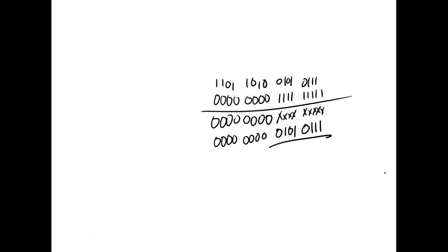So you've got to mask the first bit and work your way back. If I wanted to find out if bit 7 of this input was set or clear, I could just mask off the other bits, if that's the only one I wanted to look at. But what we have the ability to do, especially with these masks, is deal with a whole 16-bit input port at the same time. So instead of pulling in 1 bit at a time, we can bring in the whole port with 1 scan.